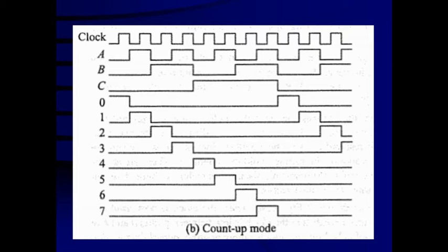And because they are strictly occurring in time sequence, they can be utilized as a control signal in any digital system or in a microprocessor where you are using a control bus. For control bus, signals such as read signal and write signal are used in a sequential form. There you can utilize this kind of time sequence waveform.